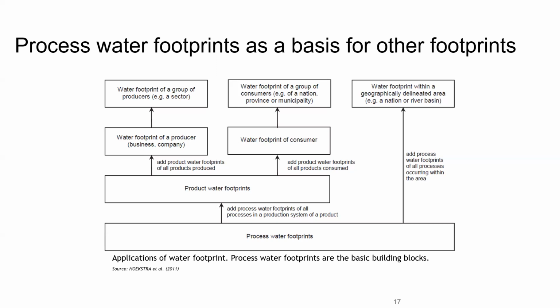Why I am saying 'if applicable' is because it is not feasible, and criteria for specific water consumption have not been fixed yet for all types of industry. In cases like chemical industry, paint, rubber, pesticide industries, multiple products are there. So when a specific water consumption is not available, you have to rely on the water audit of those industries from where you are getting the raw material. If it is an industry based on only one product, like steel, energy, distillery, the specific water consumption has been fixed. On the basis of specific water consumption, we can calculate the indirect water footprint.